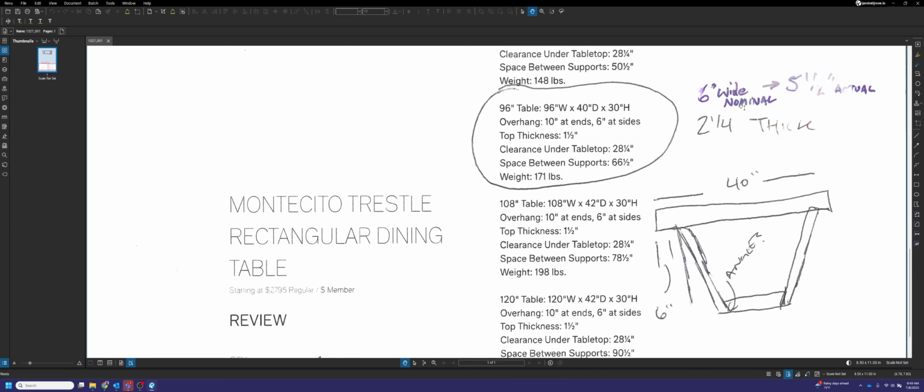So you always want to look that up before you get into drawing anything with solid, especially like planking, tongue and groove boards, slats, anything of that nature that deals with solid. Always, always, always look up online what that actual number would be. And let me see if I can pull up a chart that shows that. So nominal versus actual solid lumber chart.